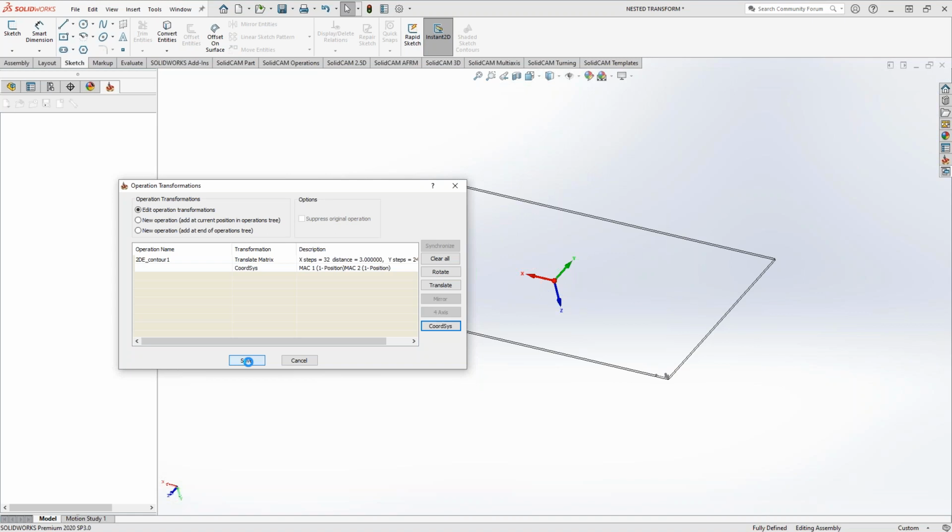So they've got maybe 4 or 8 parts that they have to machine. If the parts are all set up the same way, so the vices are on the tombstone facing the same direction, the part is oriented the same direction, then all you've got to do is program once, and every part on that tombstone, no matter what face of the tombstone it's on, will get machined in the exact same way.